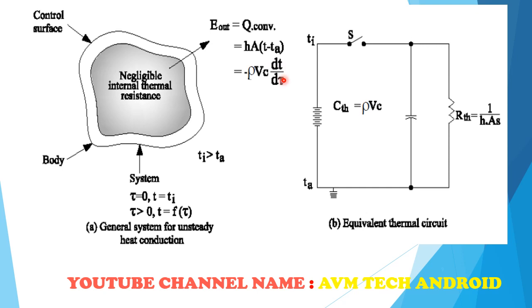So if we talk about this equivalent thermal circuit, you can see the resistance offered, that is the convection resistance, is 1 upon hA, where h is the convection heat transfer coefficient and A is the surface area. Cth, that is the thermal capacitance, is rho V c. Ti is the initial temperature, and Ta is the surrounding air temperature. So when switch S is closed,